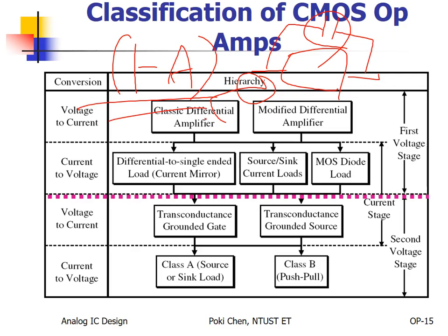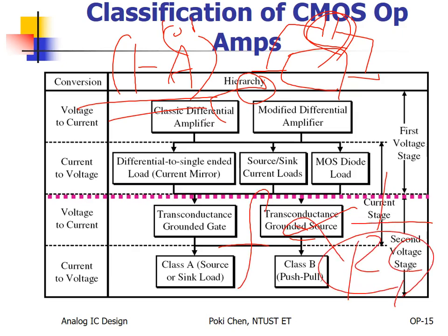So if it is 100, wow, it means what? Equivalently, such kind of parasitic capacitance will also be increased by 100 times. 100 times means what? As you know, the bandwidth is proportional to 1 over RC. The more capacitance or more resistance means the bandwidth will be substantially reduced.